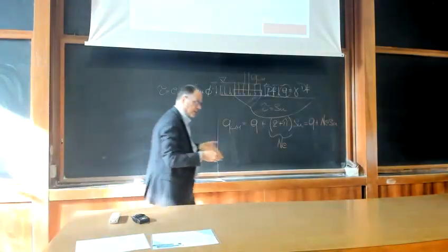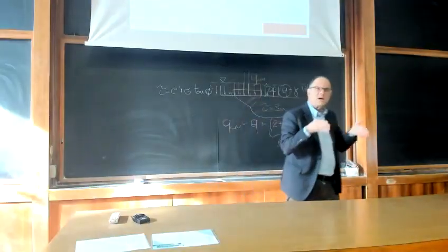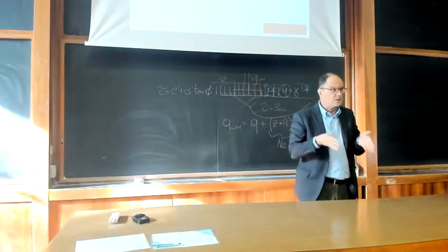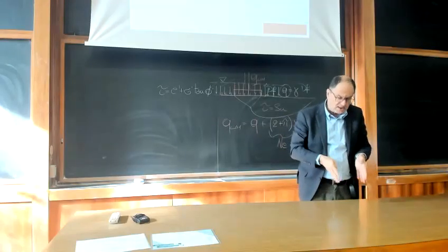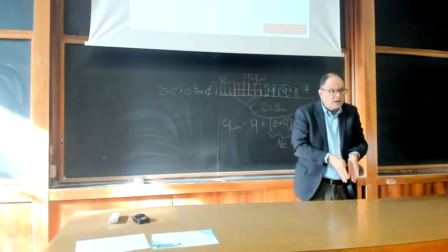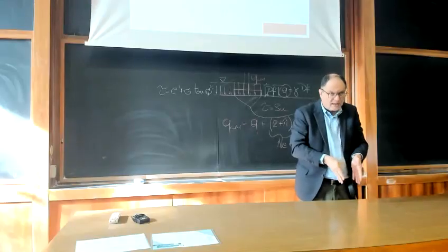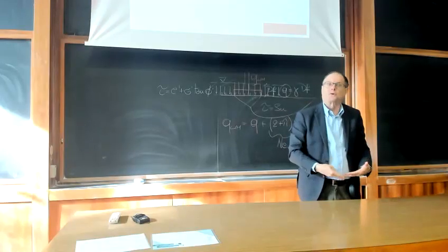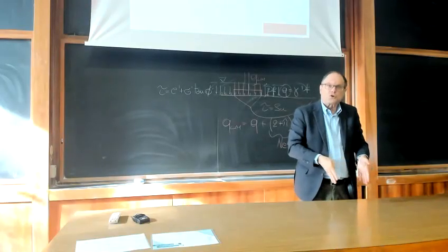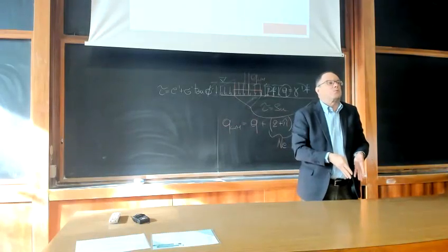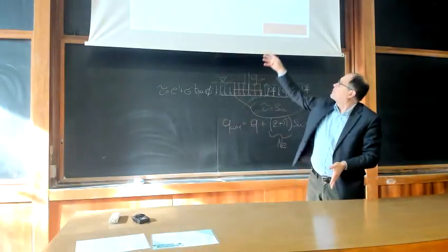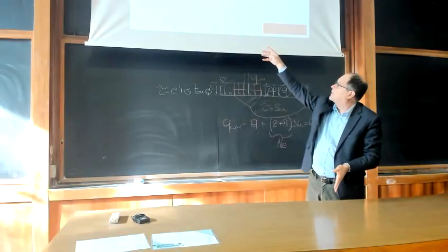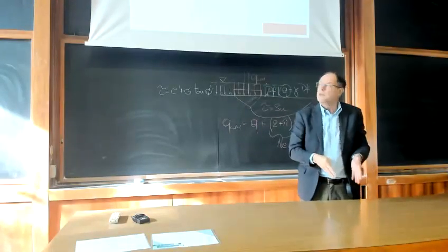Because think once again about the mechanism, the physics of the phenomenon. If you push the footing inside, we said the soil is expanding, is moving laterally to allow the footing to go down. And the expansion of the soil is exactly what we referred to yesterday. The lateral expansion is something which provides you with an active zone.